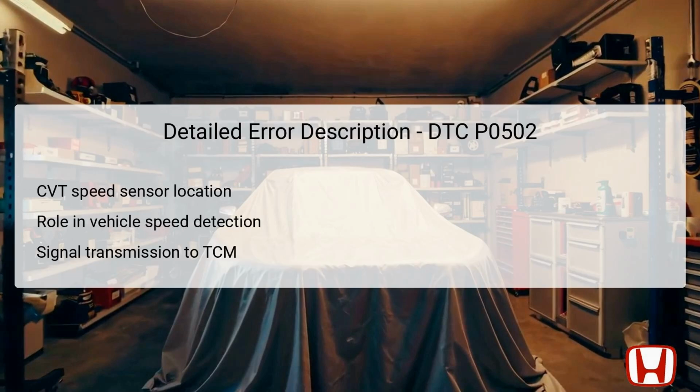The CVT speed sensor is attached to the outside of the torque converter housing, a location that is vital for accurately detecting gear rotations. Its primary role is to monitor the number of revolutions of the secondary driven gear. This information is critical as it gets sent in the form of a pulsing signal to the transmission control module, TCM. The TCM receives these pulses and utilizes them to ascertain the vehicle's speed.